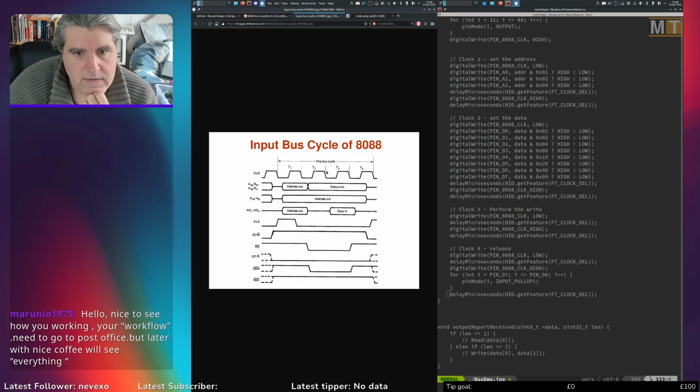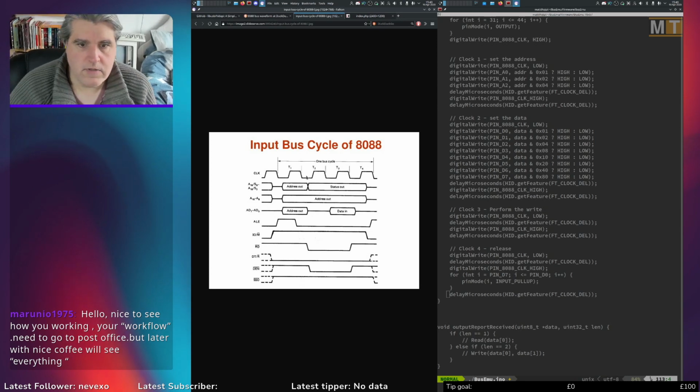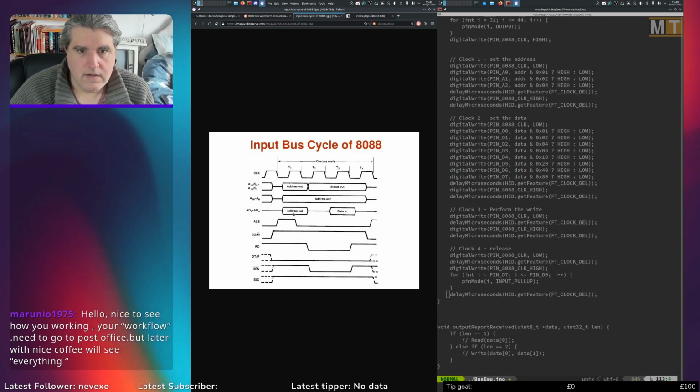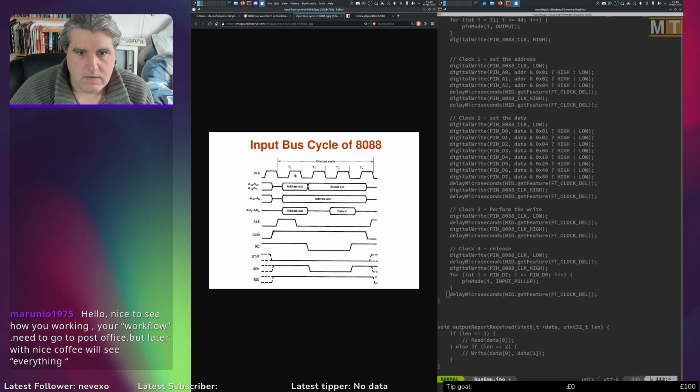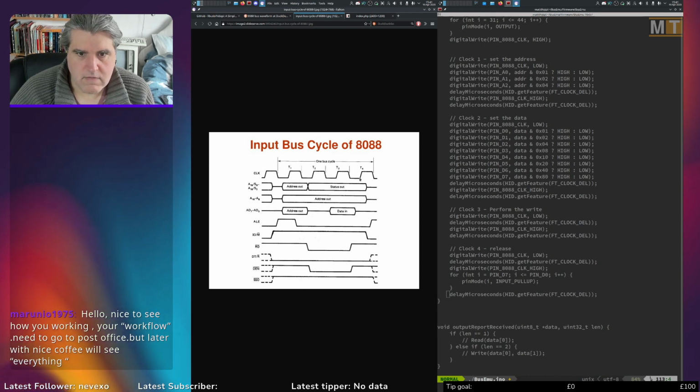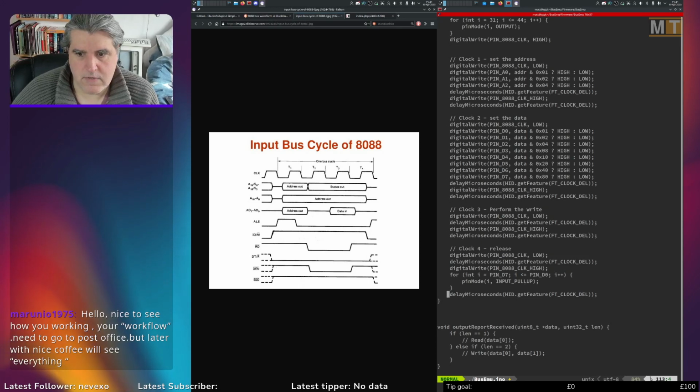Second one is setting the second part of the address. It takes 2 clock cycles to do the address. First one is from the multiplex. Second one is from the rest of it. So 2 cycles of address, clock lowers, delay, clock rises, and it will do the read at that point in T3. Clock lowers, data is released, clock rises. So that's pretty simple and straightforward.